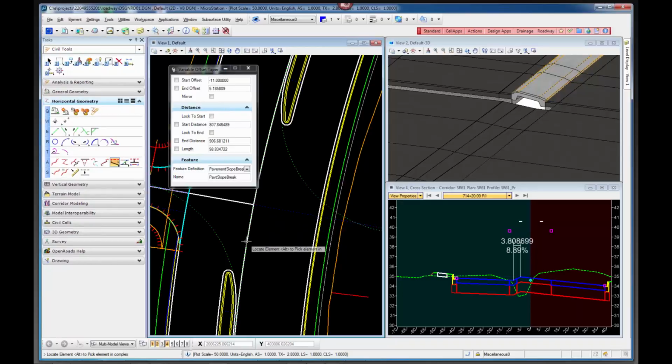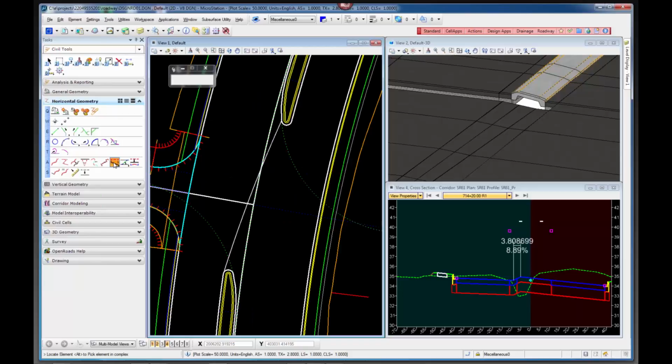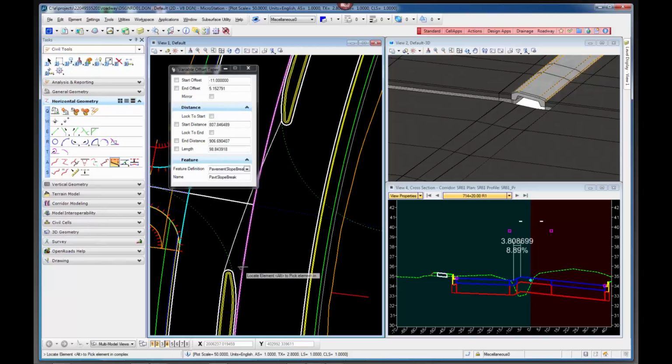So I'm going to pick the center line as the offset line, and then I'm going to snap from one point here on one side of the nose, and I'm going to go to this point over here. The reason I'm doing this is so that it stays curvilinear, and then I'm going to do this same tool again, and I'm going to go off of this line and click here, and then click to this other side,